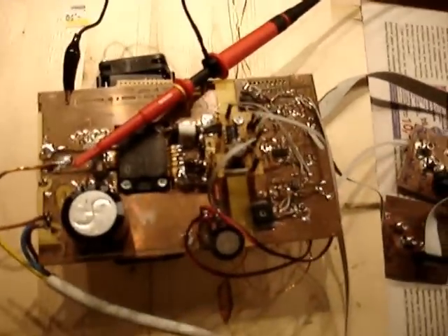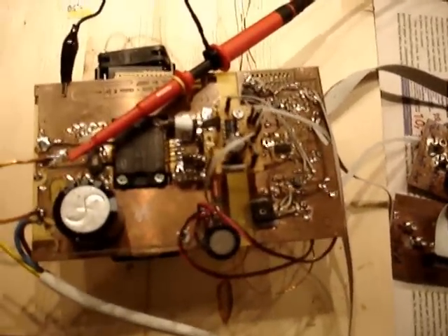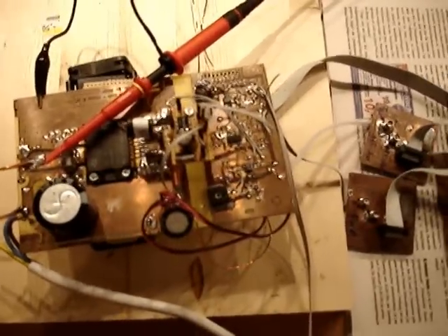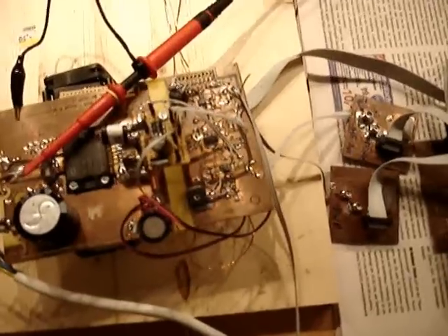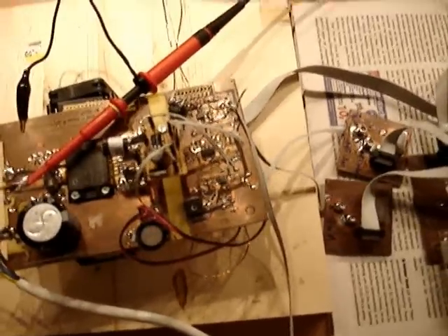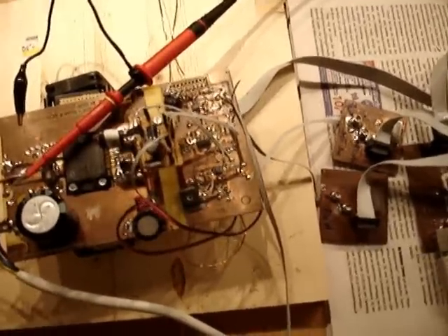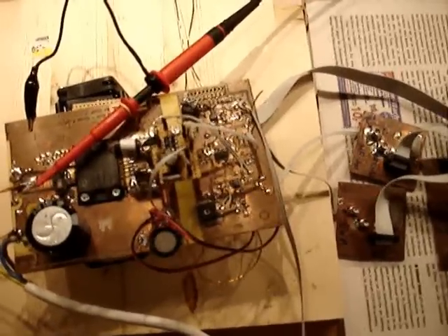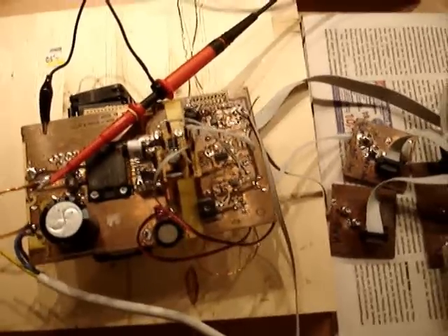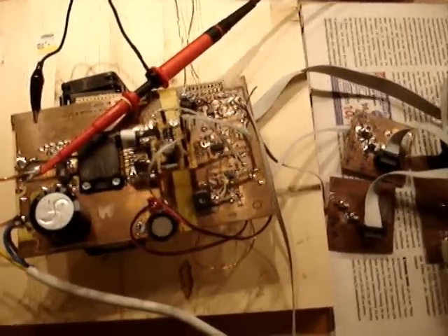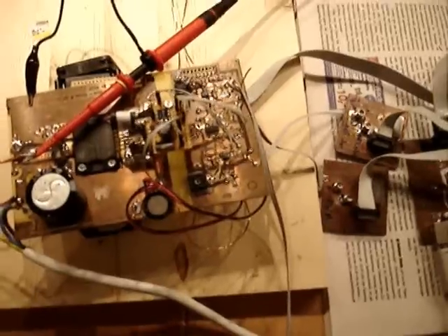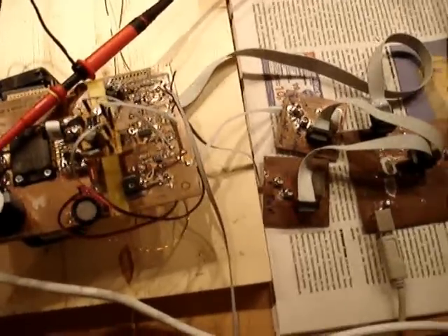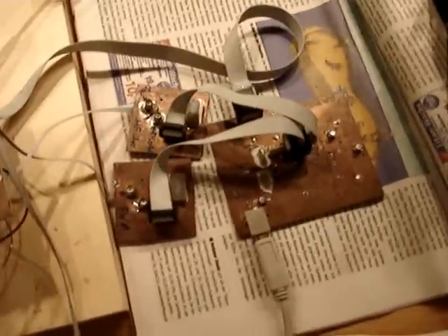The control part here is potentially isolated with a high-speed optocoupler, and the control circuit gets 2 frequencies from 2 DDS generators. The one frequency is used for setting the excitation frequency and the resonance frequency of my Tesla coil, and the other one gives the frequency for the pulse width modulation, for audio modulation. Both DDS controllers are connected to my microprocessor board here.